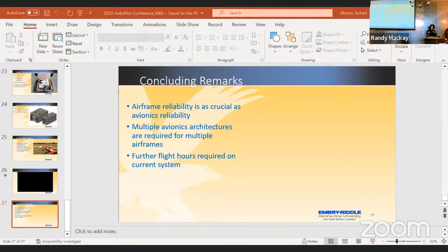Right, and just to provide some clarification in terms of what my system does currently: the backup flight computer, through the Lua script, sees an exceedance in parameters and kills the primary. Goal number one is to auto level the airframe and get it to within a cruise speed. So if it's overspeeding, it slows down. If it's stalling, it speeds up. Then it goes into either an autonomous loiter near the launch point or RTL. So just starting with the baby steps. As you said, continuing the auto mission is a whole other layer of complexity.